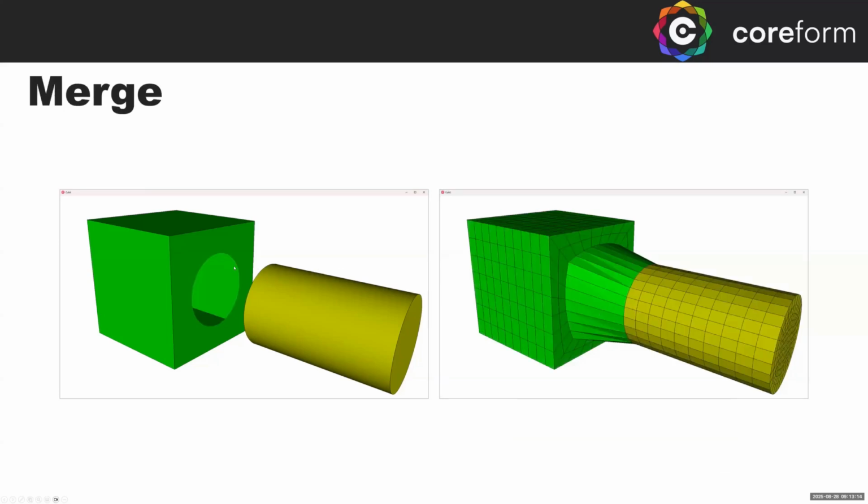What the merge operation does is it now says, hey, these two surfaces are the same surface. Remove one of them and just treat the one surface from a topology standpoint. And so you can see here very clearly that as I built this mesh on this top surface, it is now forced to use those same nodes that are on the cylinder. And you can see that even the actual black curve is missing from this circle. There's only a single curve and a single surface that represents that. And so that's why now we have this connected mesh.